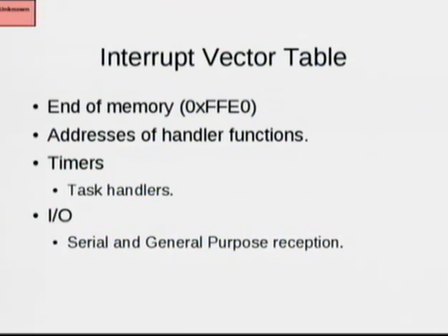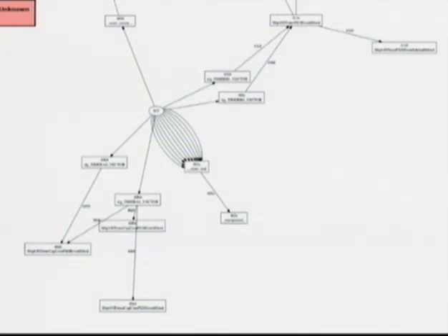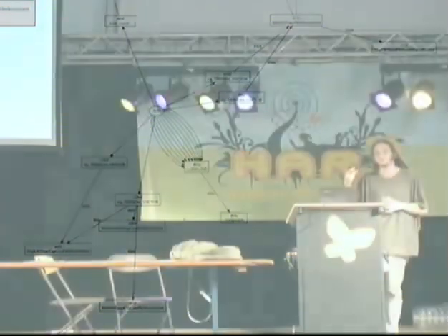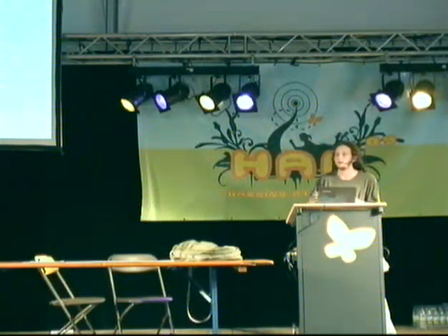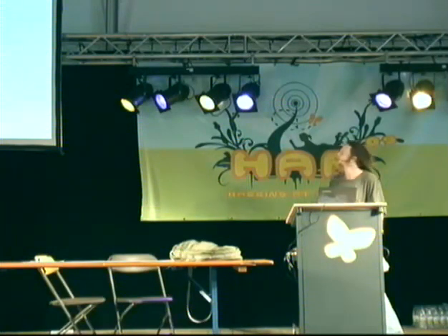So you don't do that. Instead, you put the chip to sleep, and you say, wake up and run this interrupt handler when the button gets pushed. But you can't specify which. That's done by hardware. And that makes it easy to reverse engineer. And then you can see here that these interrupt handlers are all unused. So if you see many different interrupts going to the same target, it's probably an unused handler. All it's doing is making sure that the chip doesn't crash by some invalid address being pushed in by mistake.